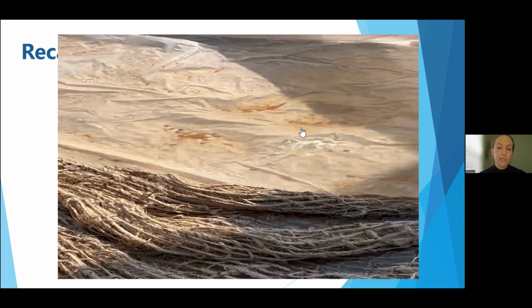And you can use a turbidity meter and add water to it and measure the before and after turbidity. But it's very dramatic, so a lot of times we'll do these even without a turbidity meter on a tailgate on site, and you'll be able to visibly see which one reacts with the soil and forms those big flocks. Okay, and I guess just a follow-up question, why would one PAM work and another not? What's going on chemically?